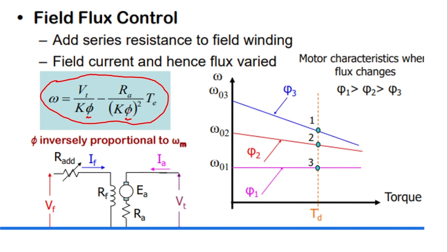And from here now, since the flux is at the bottom and omega on top, that is an inverse proportion relationship. So as flux increases, the speed will decrease because it's inversely proportional. Yeah, so if you decrease the flux, you increase the speed. That's inversely proportional.